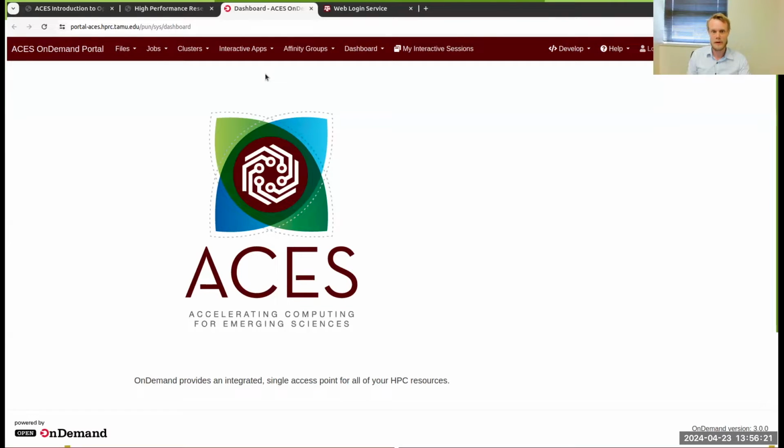So there are a bunch of things you can do here. You can access the cluster directly. A shell access is through there. We're going to do today's tutorial through a VNC session. The reason I want to do that is I want to be able to run Paraview together with OpenFOAM. OpenFOAM doesn't really require any graphical user interface to run, but if you want to be able to look at what you are doing, we want to have Paraview open as well in the background.